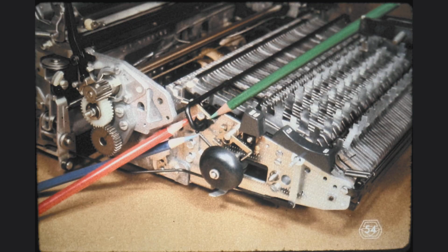The next item on our agenda is the removal of the bell ringer bail. First, we must disconnect one end of the bell ringer bail restoring spring indicated by the blue pencil. Then, we loosen the screw indicated by the red pencil. This will enable us to slide the bell ringer bail toward the right and thus remove it from the right side keyboard frame. When you remove the bell ringer bail at the right side, be sure not to lose the bearing washer indicated by the green pencil.